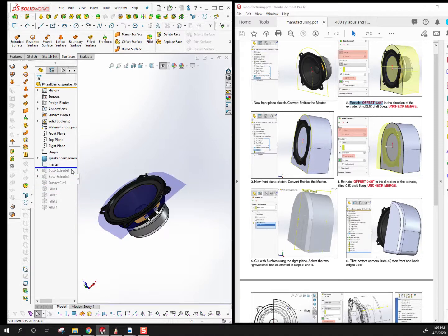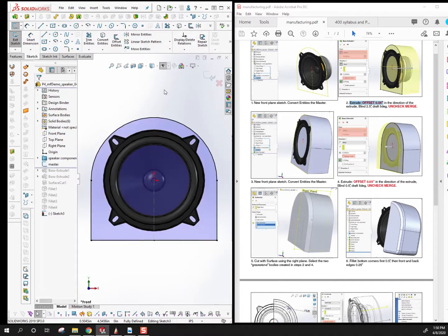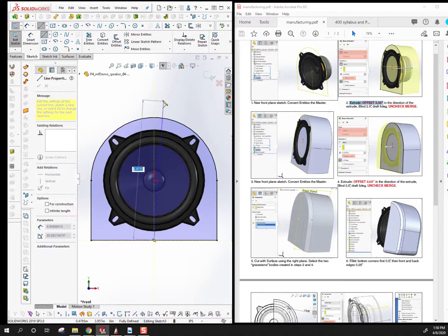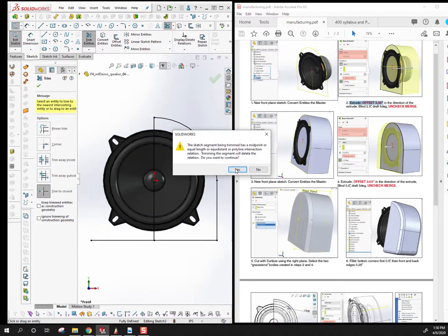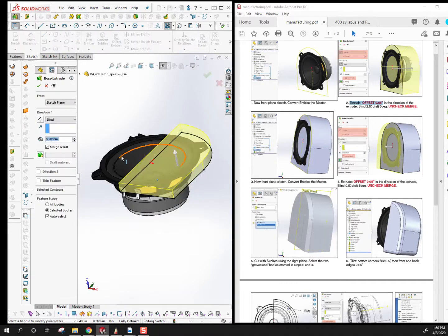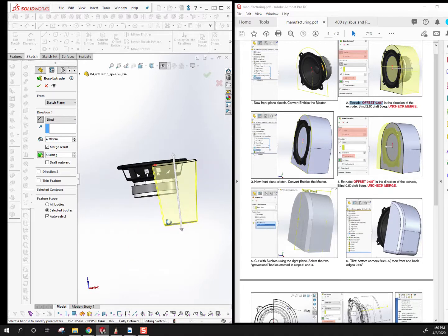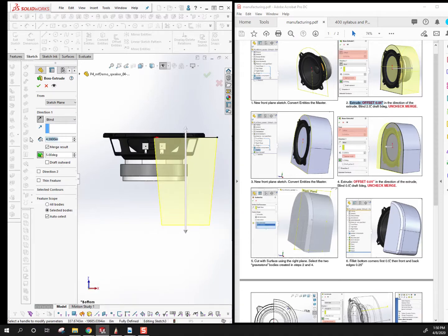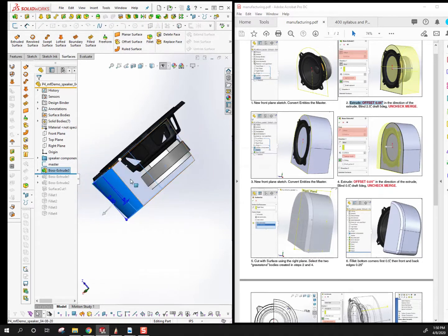As a side note, let me show you what it would look like if we just extruded half of it to begin with. So if I take the master here and I copy it, and then let's say I want to save a step and just extrude it in half to begin with. The issue here is if I put draft on this, do you see it puts draft on this inside face as well? Right, so if I match this distance, 2.5, these faces are all the same, and that's good. This interface is also drafted.